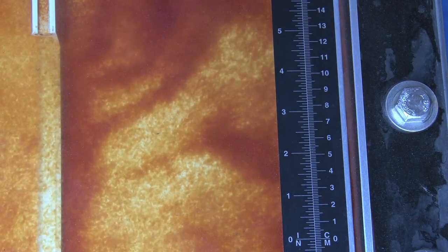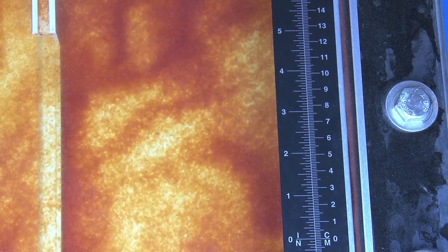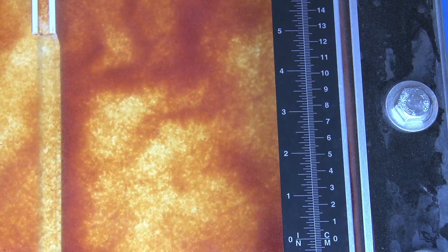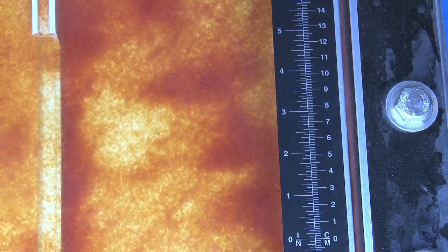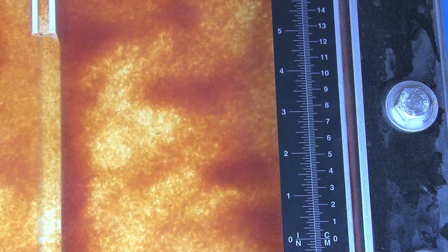And here is the video of the innovative EcoFlow design. Feed enters at the sides of the plates. Solids slide down the plates without disturbance and drop into the sludge hopper. Sludge re-entrainment is avoided by segregating the feed and sludge, permitting the existence of two laminar flows. EcoFlow is the first improvement in inclined plate settlers in over 40 years.